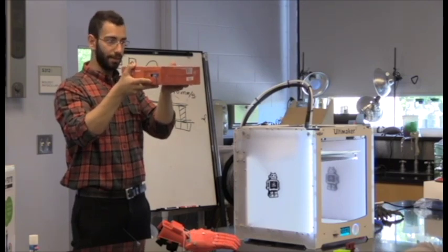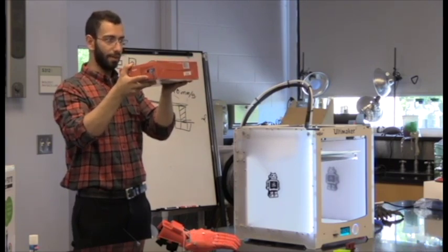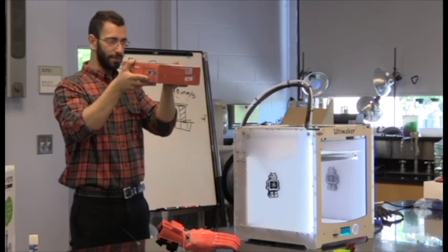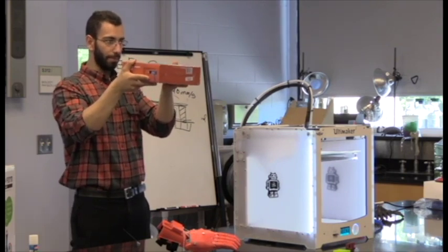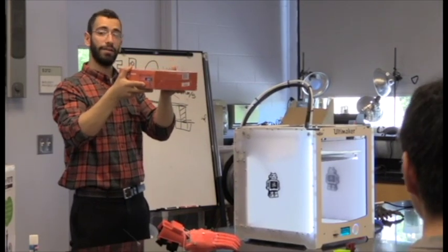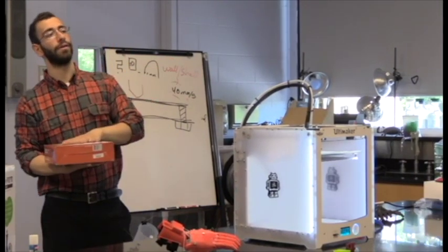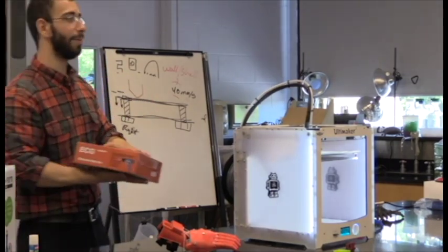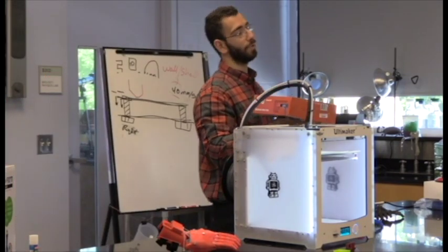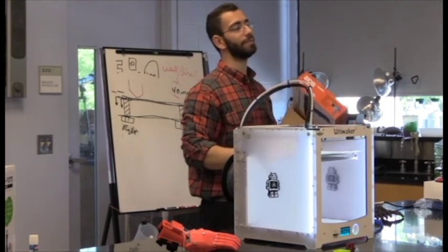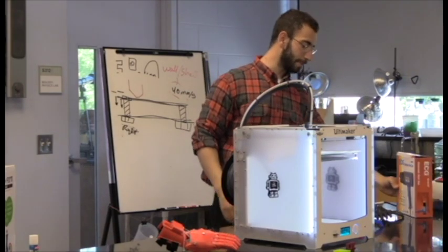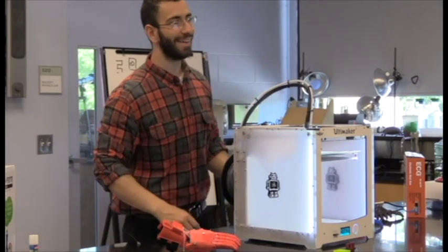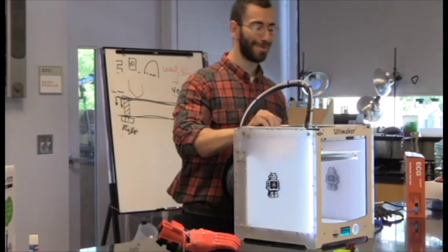So sometimes at the end, this guy first tunes the back, then you can fix the front and the other front. So this usually works. But sometimes when you adjust this a little more at the end, it might twist the whole bed. And the bed, again, is the most crucial part that you have to calibrate for a successful print. That will take time, but once you got it, it will print. If you don't spend time on that, the 24 hours you spend printing are going to be pointless. Okay? I promise. Been down that rabbit hole.